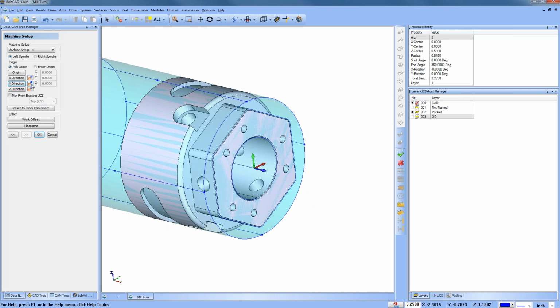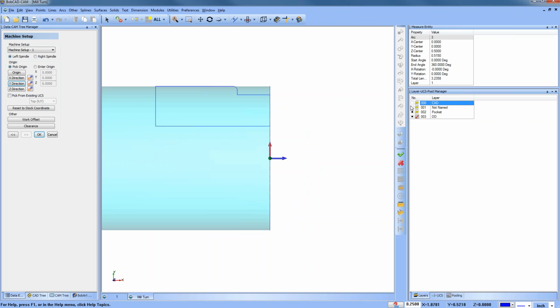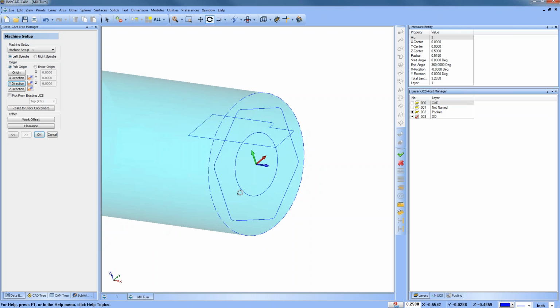I'm not positive of the rhyme or reason for it, but I know that I want my axis to be my Z, negative going back, and I know that this point here is going to be my x-axis because that's where I have my OD part geometry laid up, okay? So hopefully that makes sense. And again, the orientation that I have the part in is by my choosing. You can have the part in any orientation, but your turning profiles need to be in the XZ plane, and your axis is the Z, okay?